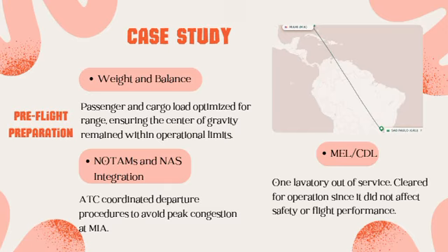And then the MEL and CDL. The MEL permitted operations with one inoperative lavatory, as it did not impact critical safety systems. This ensured the aircraft remained airworthy without delaying the flight. So MEL considerations enabled the flight to operate efficiently despite minor equipment issues.